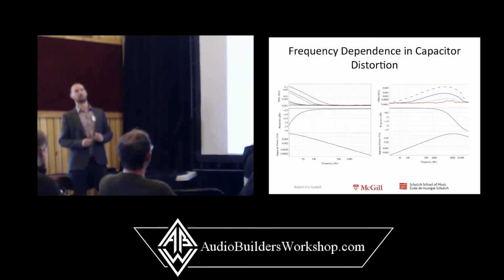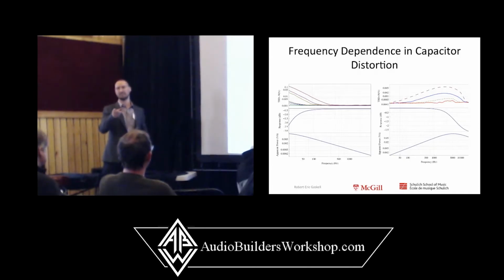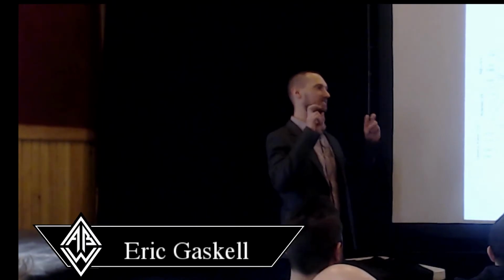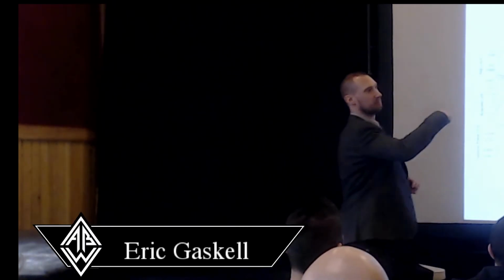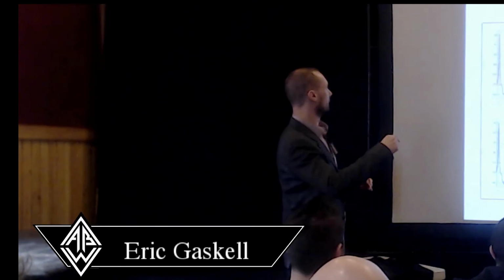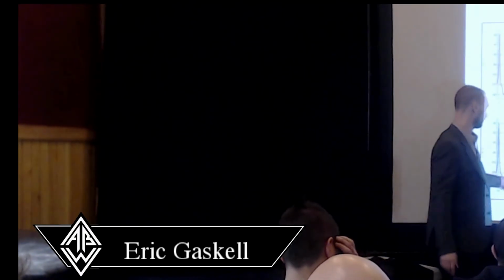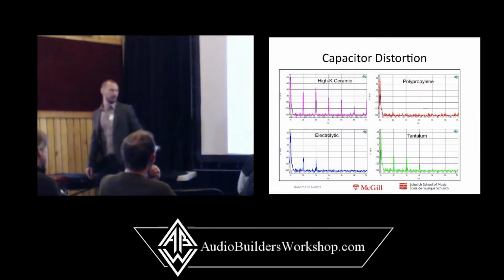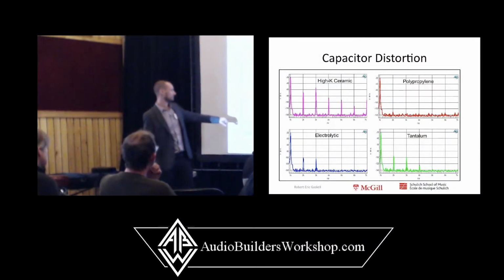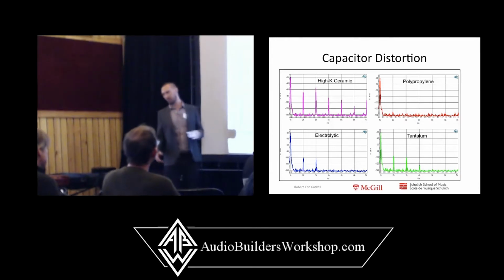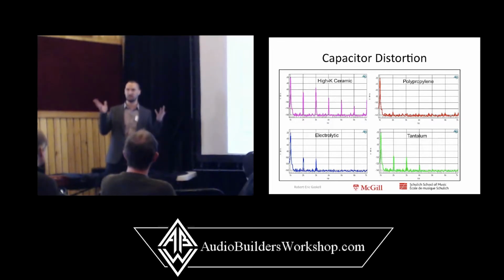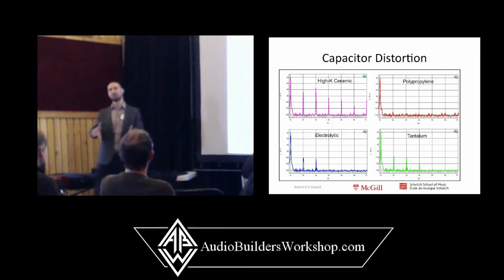In the distortion test, did you do anything differently? Did you do some where the capacitors were biased, the polarized capacitors, and then not biased? I did, actually, and that was one of the reasons. I don't know if you've read that Cyril Bateman paper. No. It's an excellent series of papers called Capacitor Sound. If you go back to the previous slide, please. What happens is when you bias this with like 50 volts, the second harmonic distortion shoots up. It can increase by almost 20 dB.